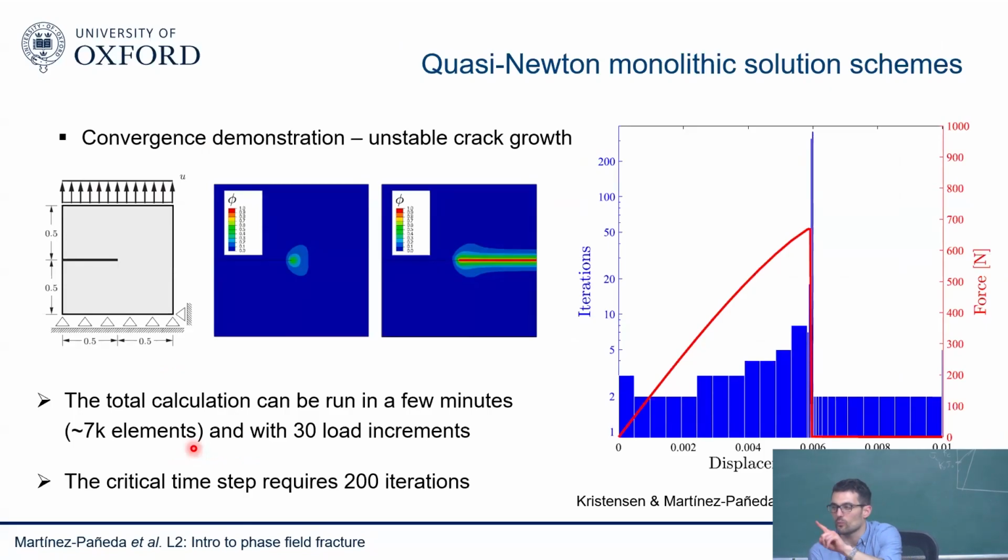Sorry, one second. One thing that came to my mind, the line search. When we started doing this work, we did it in Abaqus because Abaqus has it all implemented. So we just touched a button and said, oh, wow, this works so nicely, the BFGS. Then some people have tried since our paper to reproduce it in their own codes. I was told a few groups have managed to get this very good behavior, but I was told that you have to do it exactly as Abaqus does. So this particular BFGS implementation, and you need to put a line search, which Abaqus has already inbuilt as well. So that's one aspect.